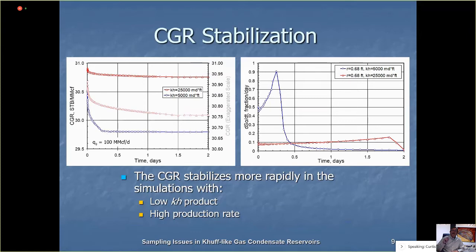And by the way, this is also the same kind of thing that you see for MDT open hole formation testing as well, but there it builds up even more rapidly. You can draw down below the dew point, but because it's spherical flow, region 1 is more like a sphere instead of a cylinder. So it takes less time to reach this kind of stabilized CGR.